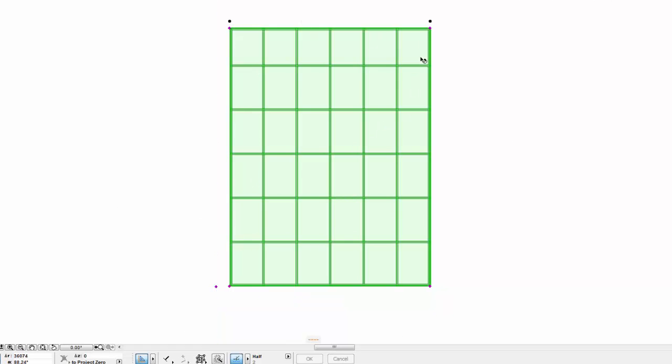In this first stage, which is guide off, I've taken out all the hotspots and all that sort of thing, so it's very uncluttered. Now you might want me to put those hotspots back in because you may wish to dimension to the joints, so you might want those joint hotspots in there. They are dynamic, and therefore you can associate the dimensioning to them, and the dimensions will change with the design.